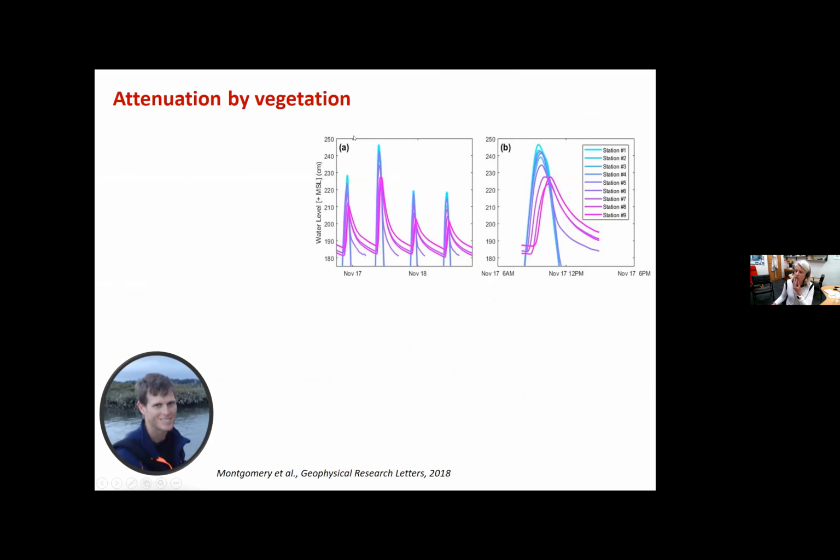And what he showed in this transect, as he moved from the outer region to the inner region of the intertidal, is the measurements of how much the storm surge was, in case it was a very high tide. That storm surge varied as he moved across the intertidal. And so that dropped probably around, I think he measured it as about 30% reduction across a kilometer of the storm surge that happened during that deployment.